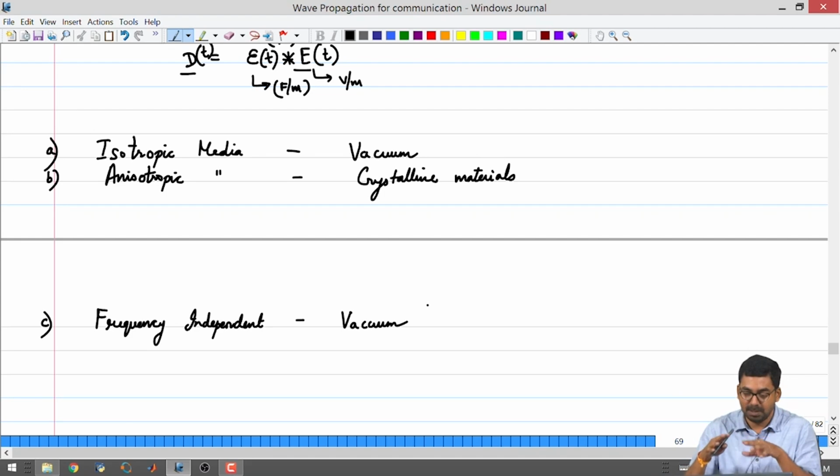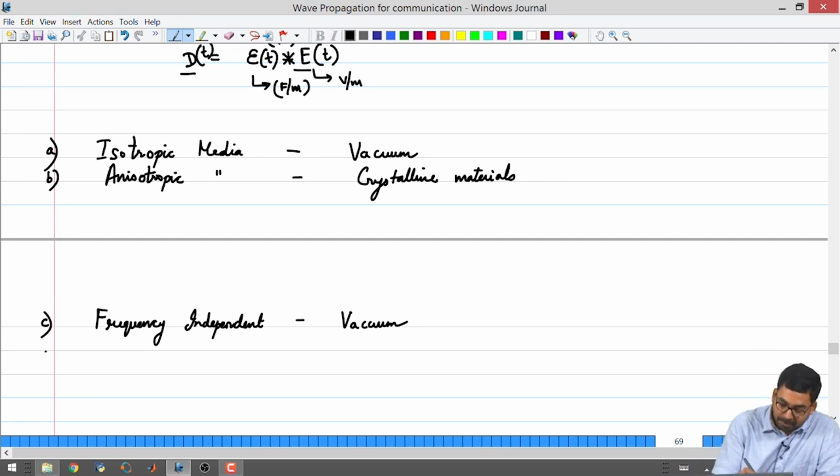Okay. So in a small range there can be frequency independence, but in a broad range, for example, we went from 1 megahertz to 1 gigahertz, using the same values of RLGC is not usually appropriate. Right. You multiplied the frequency 1000 times, you will have to recalculate what RLGC is with standard methods. Okay. So frequency independent is a good assumption for doing paper level work. Right? And to simplify math, it's a fine way to do it.